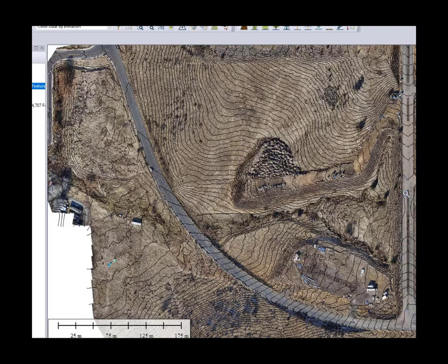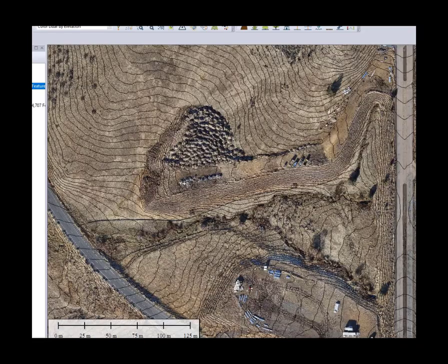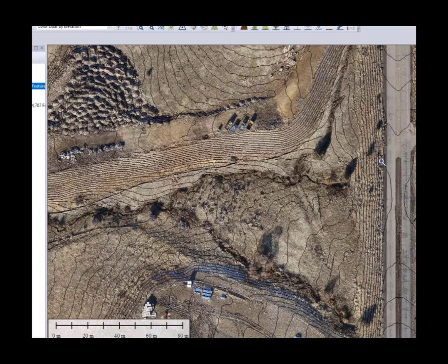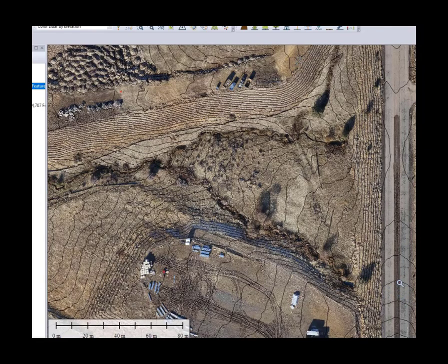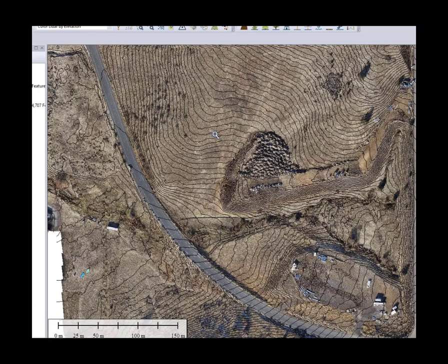This is a downslope coming into a sag point, low point, and then climbing back up. The road also has a crown to it. So you can see how the contours are coming in at the sag point, but they don't quite reach the crown height. And the contours are reflecting the surface slope and the crown of the road.